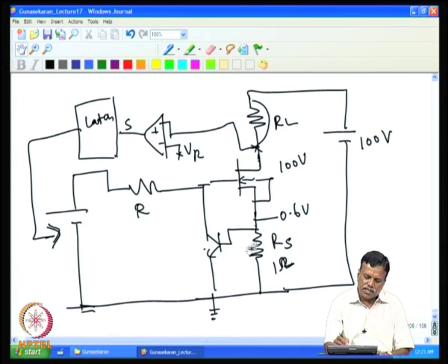So if I have this plus this arrangement, this arrangement limits the current during that 2 microseconds, such that the current will not go more than 0.6 ampere. So the current is limited to 0.6 ampere, and then this takes over and switches off the source itself, and that way the MOSFET can be protected without damage. So this combination of shutdown plus current limiting is a useful technique in MOSFET power protection.